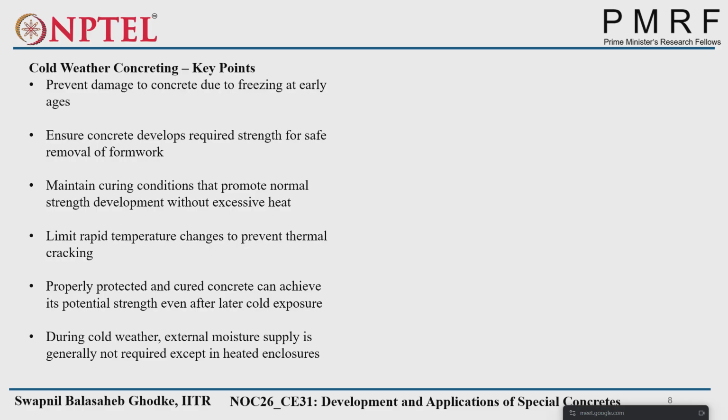Because in cold weather conditions, hydration will be slow. Suppose according to the Indian Standard Code we remove the formwork for a slab after 21 days; maybe it will require more days in colder weather. So on-site visual inspections are required for that purpose. Maintain curing condition.